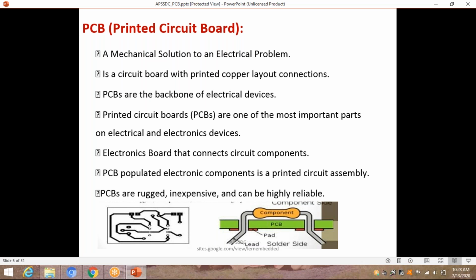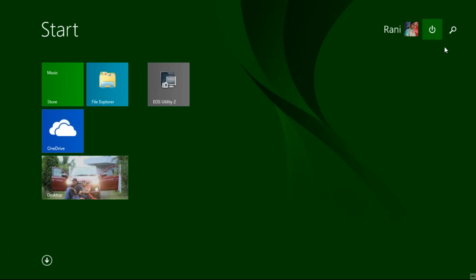You will connect the ground directly to the LED, the battery positive is connected to the switch, and the other terminal is connected to the anode terminal of the LED. Guys, am I clear? Yes, sir. You can build this circuit very easily by using a breadboard.